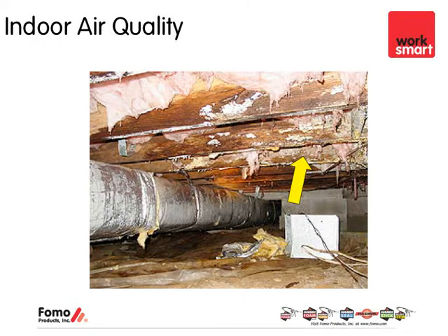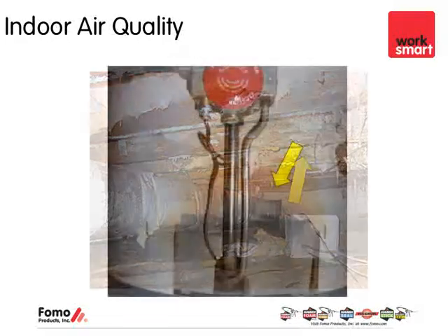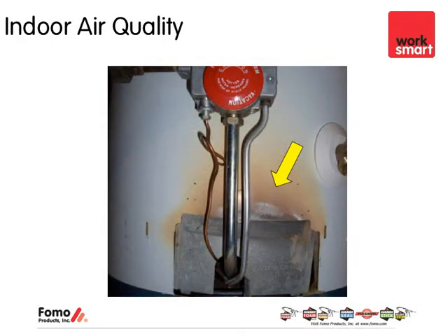In this case right here, if you think about the stack effect, air could get pulled up into the house, and that obviously provides poor indoor air quality. You don't want those mold spores entering the house. Also related to indoor air quality, in this picture you can see this is actually a hot water tank. And what you see on the hot water tank here is charring, and this is where the combustion flame is actually being pulled outside of the hot water tank and charring the outside of the tank.